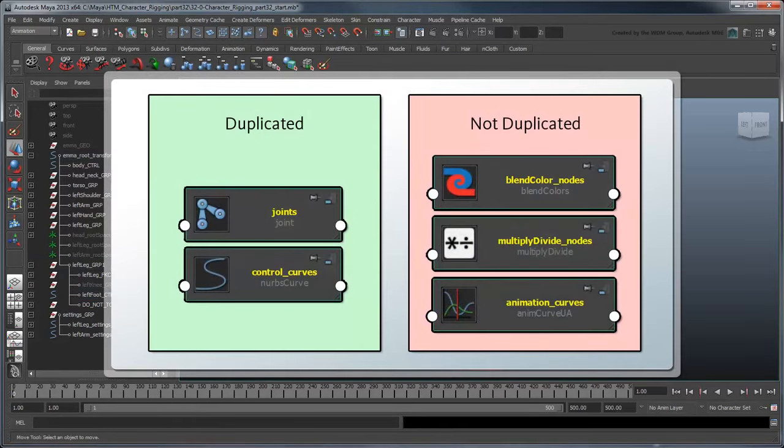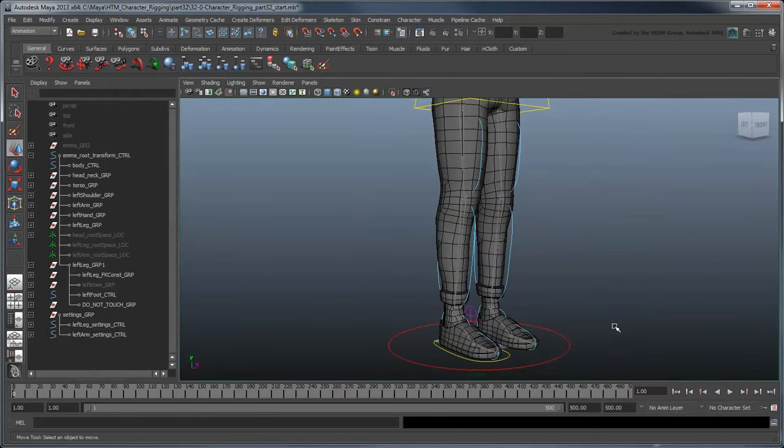This happens because we didn't duplicate the input connections along with the joints, which cut any connectivity between them, such as the FK-IK blending mode, the no-flip pole vector knee, and the joint scaling. So if we could just duplicate those connections along with the joints, then mirror them, that should be sufficient for the right side, right? Let's try it.